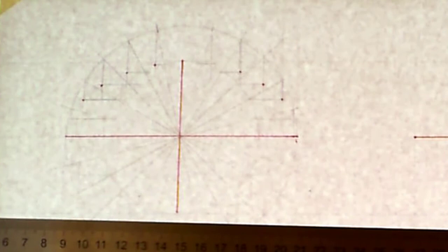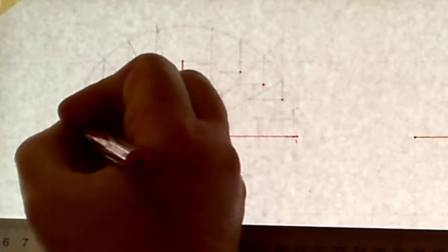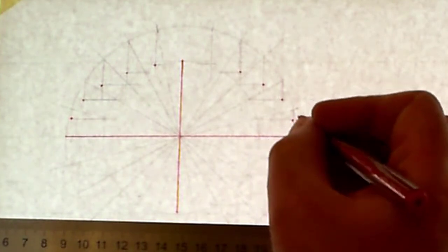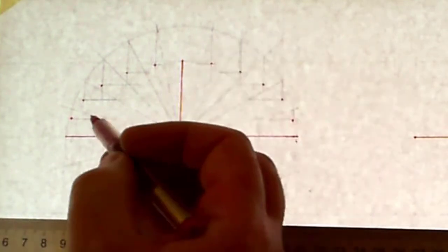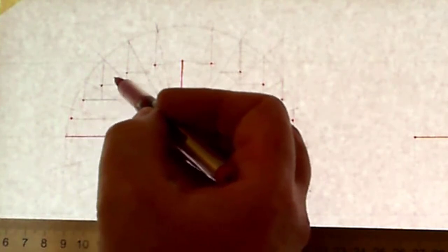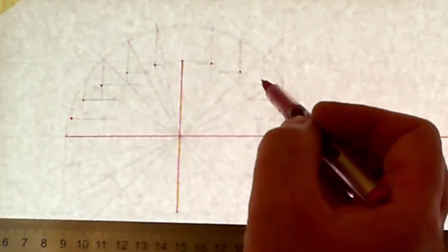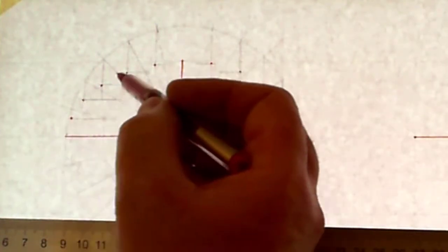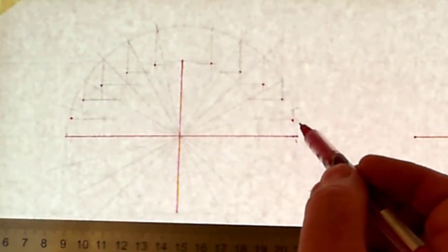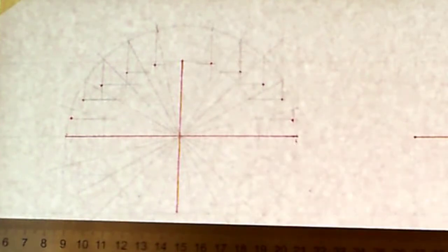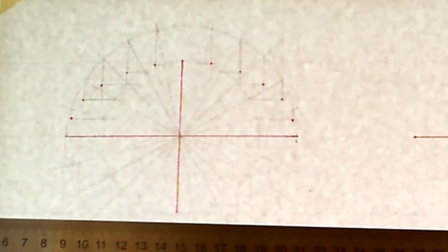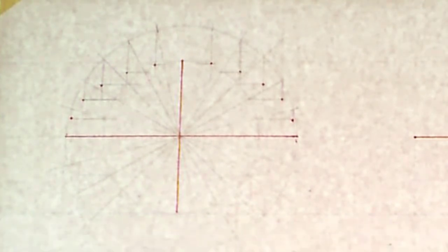So if I put those points in here, I have this point here, and this point here, and this point here. So I've got 1, 2, 3, 4, 5, 6, 7, 8, 9, 10, 11, 12. I have 13 points here going right around by way of the semi-ellipse here. Okay, now I'm going to just simply do the same now on the bottom, and before I then proceed to draw it in by way of hard lines.